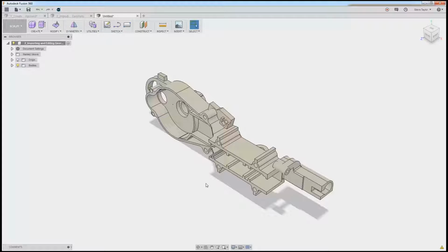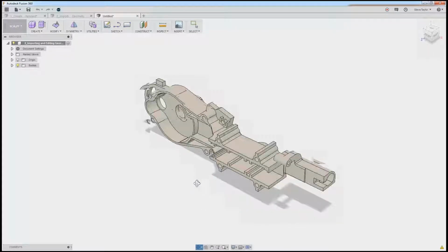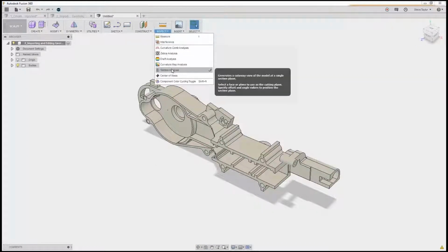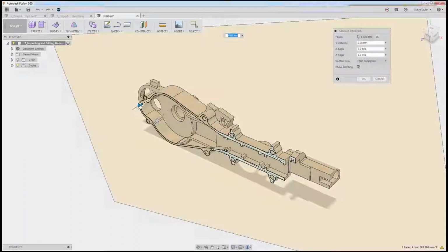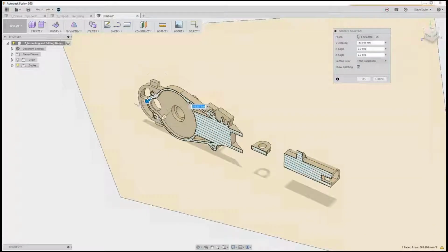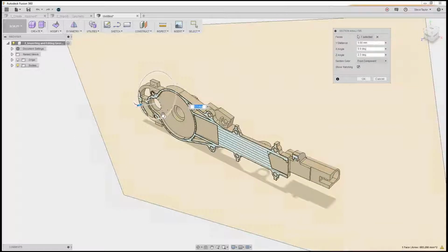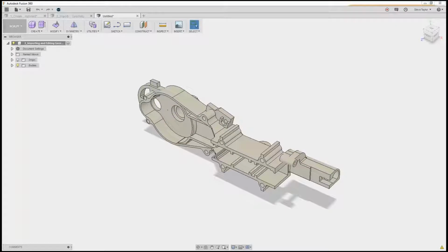And you can see it actually opened pretty quickly, and you see it's been able to stitch it into this solid model. If I wanted to check it was solid, if I go into Inspect and go into Section Analysis, pick up on a face, then you can actually see it has brought it through as a solid. I can spin that around. So you can see there we've actually got a solid model from the IGES file. It's a very quick and easy way to check that. I'll take a look at the body.